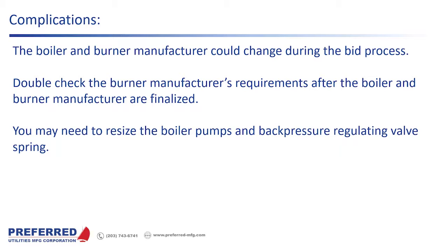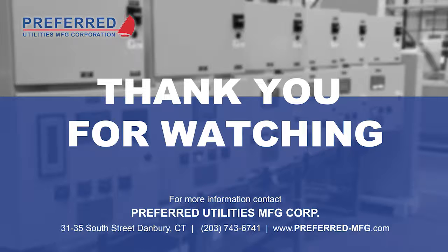But on new construction, make sure that you get the burner make and model number after the boilers are awarded to make sure that it's the same type of atomization or the same type of burner that you designed the transfer pumps for, so that you can fix it on paper before it gets out to the field. That's virtually everything I know about transfer pump sizing for boilers.